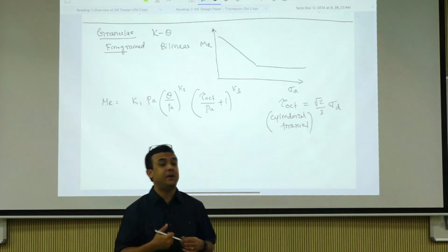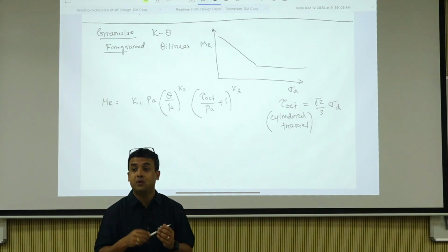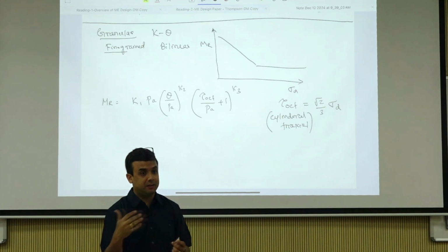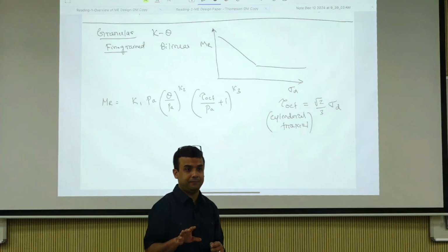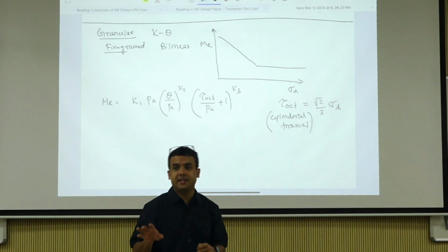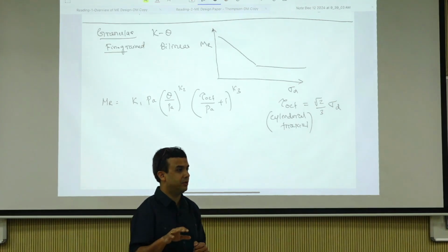That is the reason for the MEPDG trial version of the software. There was actually a version that came with the finite element part built into it, and it was just prohibitively long to run. So that is the reason they eliminated it. Now it's a layered elastic program.